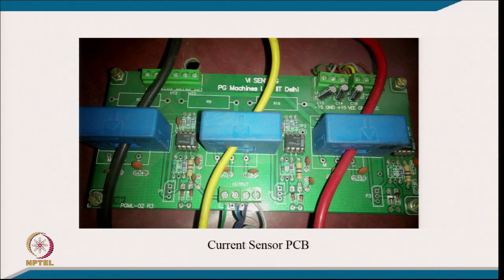This is the current sensor, an Alpha current sensor PCB. There are a lot of kinds of current sensors. This one is maybe PCB mounted, up to 25 ampere. This is typically a 50 ampere current sensor, but you might have 300 or 3 kilo ampere depending on the rating, and the thick wire going through it is the power circuit. On the secondary side, of course, we have a complete circuit which gives a sense signal to us.